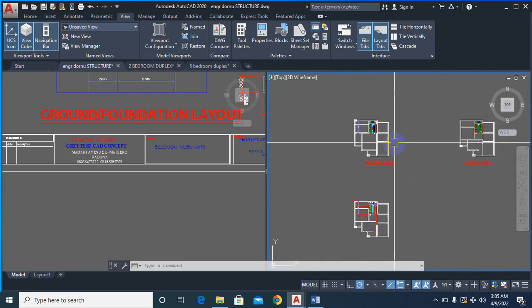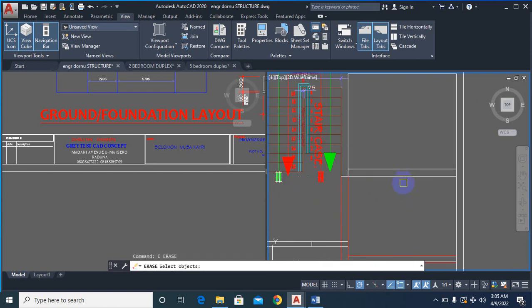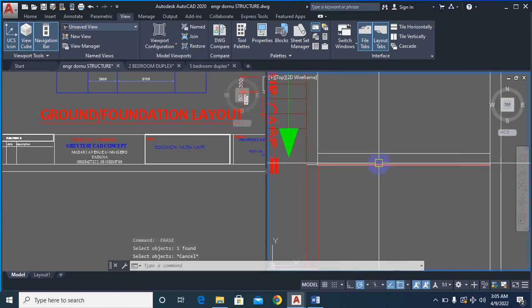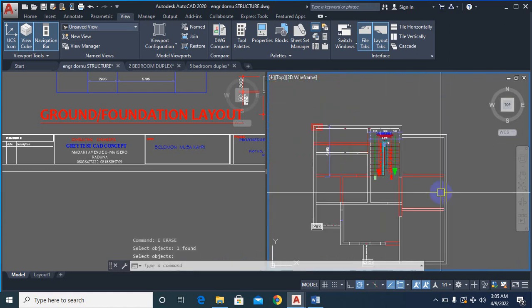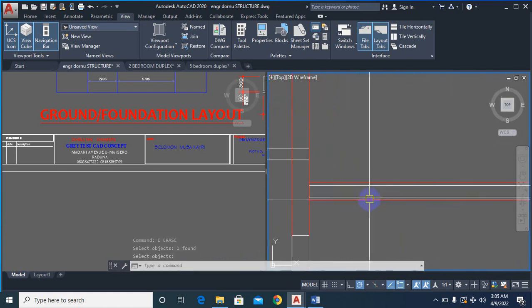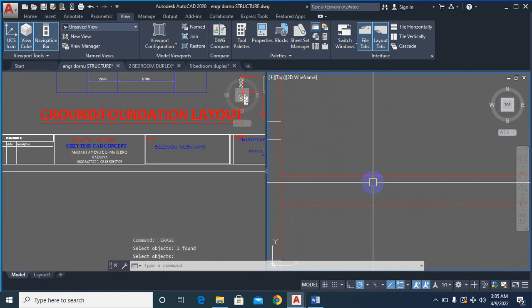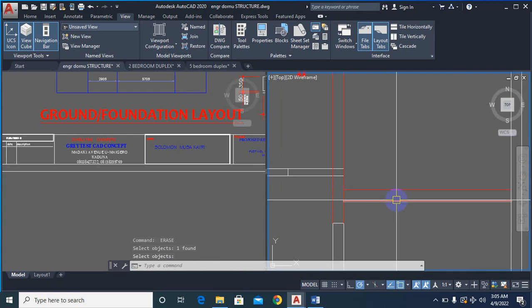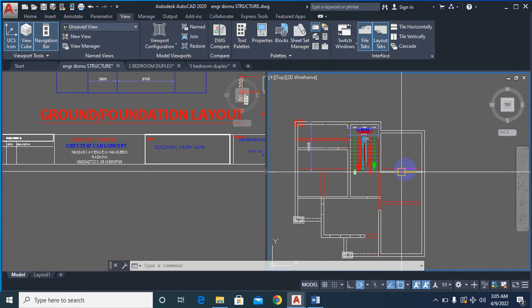Here, I think this wall, let me delete the white that is up. Good, now you can see they are together. There is a wall on the ground floor that aligns with the one on the first floor. This one will also align because this is a 150, so I change it to 230 because the size of beam we are going to be using is 230 width of beam.